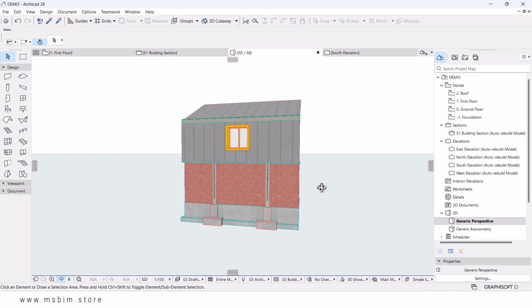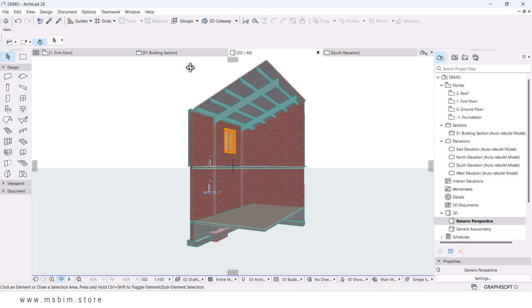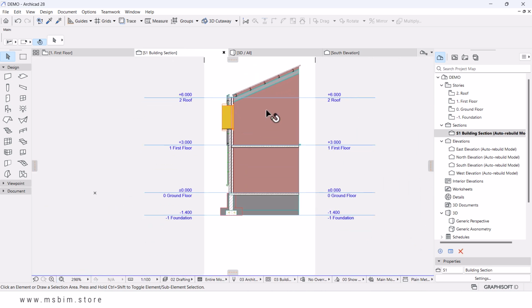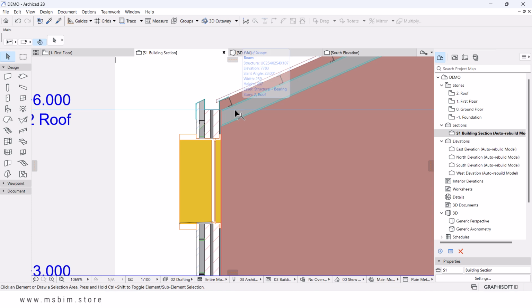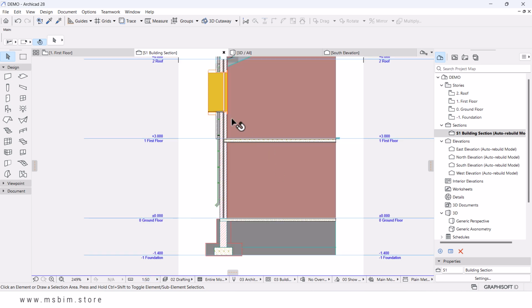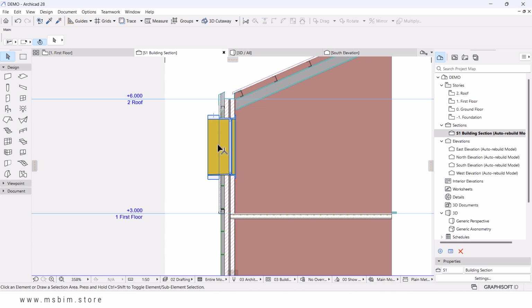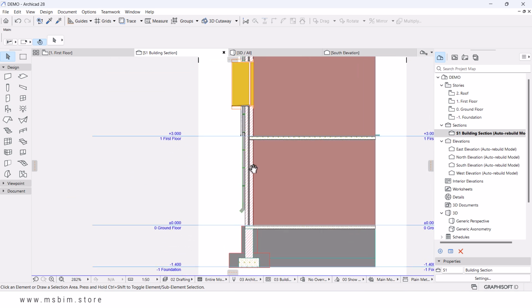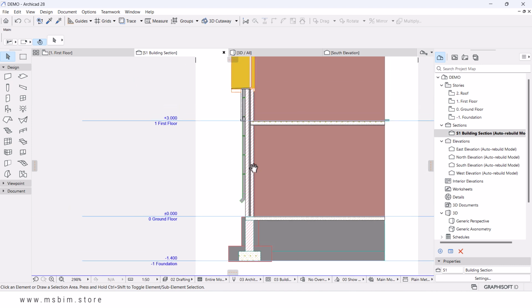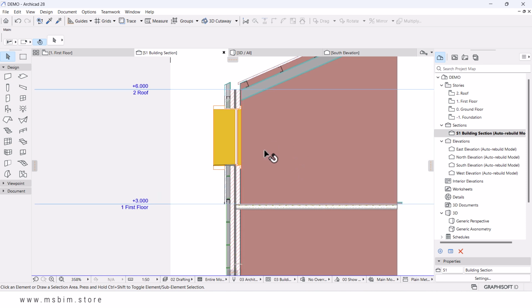So if you look at this, everything here is on default, right? You see different sorts of colors, even for your sections. You have these funny colors. By the way, the section needs to be on 1:50 scale, so I'm going to change this to 1:50 to blow up the details a bit. So we're going to adjust most of the things here in your fields. We're going to adjust maybe the scale and do a bunch of things. Okay, so like I'm saying, you need to start off by looking at the pen sets, which is your line weight.